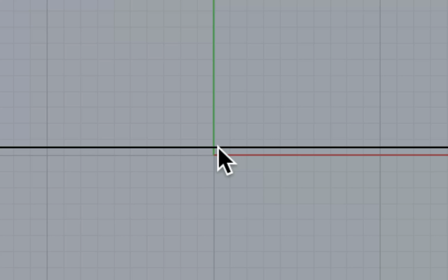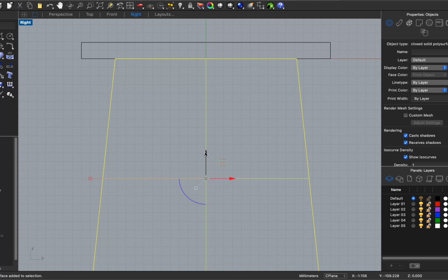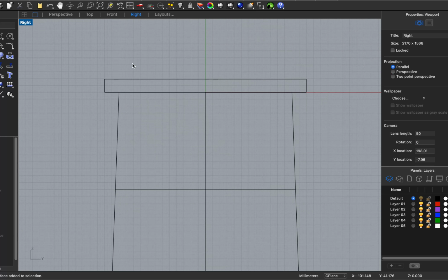And when it's done, I'll move these pieces up together. When it's almost touching, the same thing happened here. It needs to align about 0.5 mm, so I need to align the first 0.5 to have them perfectly aligned. And then I've got to observe if this is the shape I want. I will then confirm. But now I'm not very happy with the angle, so I think I'd like to extend a little bit outward. Alright, I'm not happy with this. So once done, we will then cut out the mortise and tenon.